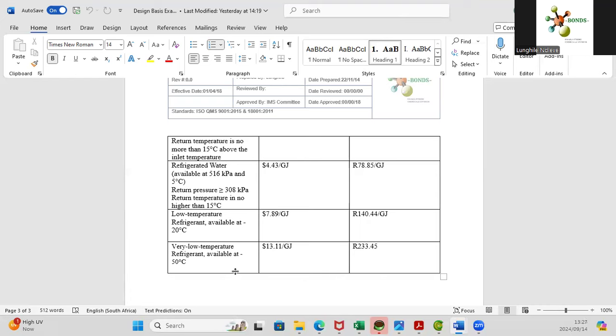That's why it needs to be in your design basis, because you know immediately once you come across a situation where, for example, a separation process requires you to be at minus 65 degrees, feasibility falls out the window. You can no longer do that, right?